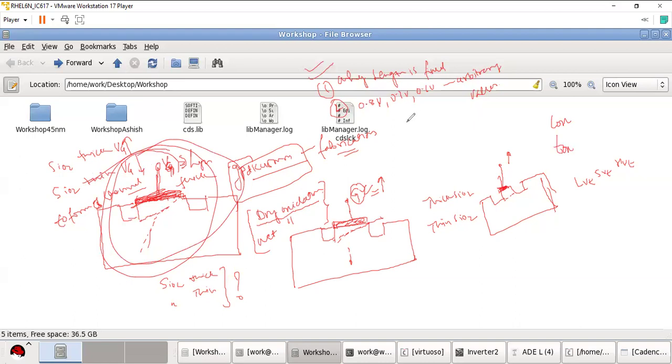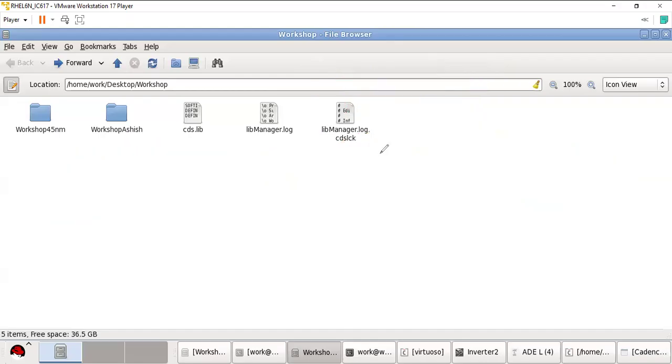And the only thing that you can change during fabrication is the width of the MOSFET, right? So the point is that not only the length is fixed, but all the parameters that I use in my MOSFET are fixed except the width. And when I increase the width, the drain current increases. When the drain current increases, the power dissipation increases. When the drain current increases, the delay in the circuit reduces, it comes down.